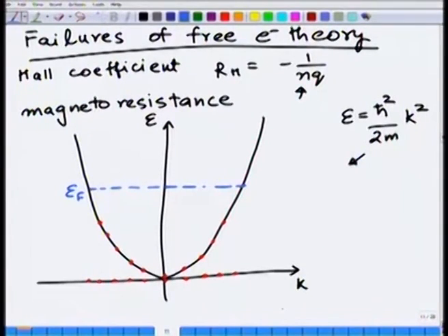That is what I have shown you. The question is, what is this quantity? You also remember I have pointed out that this is an E-K diagram, meaning an energy versus momentum diagram. K precisely represents momentum as well; h bar multiplied by K represents momentum. So if I get a proper E-K diagram for each material, then I have energy and momentum. Those two quantities are sufficient to do all the dynamics we want to do. Whatever you want to do with the dynamics of an electron, you can do if you have an E-K diagram. So essentially, for real materials, I want to get these E-K diagrams, and in order to understand this E-K diagram, I must understand K.